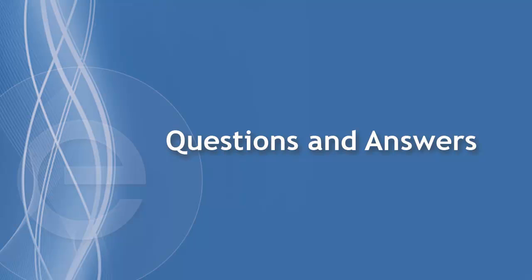I'll take a couple questions here. There's a question about solar farm requiring reverse power protection. I don't think that would be an issue, although it would probably be a function provided in the interconnection relay. As we mentioned, reverse power is an issue for the prime mover. We're talking about synchronous generators here for the most part today. The set point for the negative sequence current is going to depend on the generator, and there should be guidelines provided by the generator supplier. In the IEEE guide, there are also recommendations.